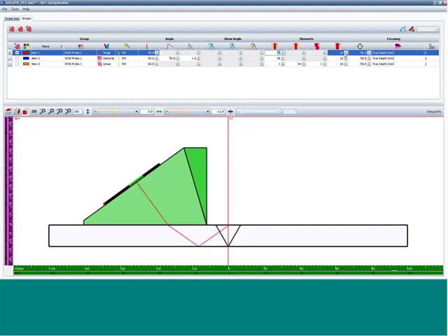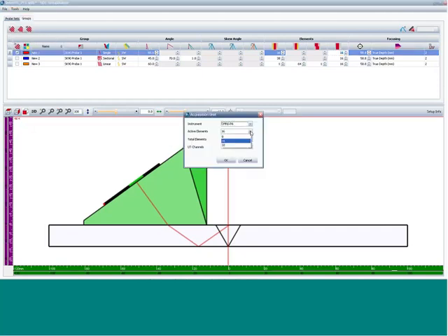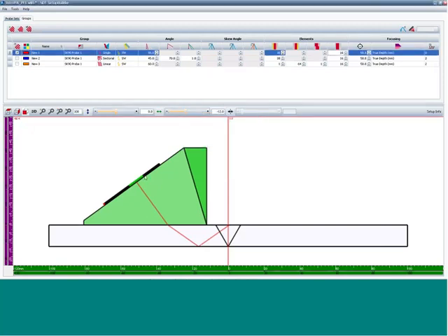Okay? I'm limited in my configuration now. I cannot type in a larger number than 16. Were I using an acquisition unit with more capacity, then I would have the ability to use more elements. So I have a focus distance here of 50 millimeters in true depth. One static focal law group.